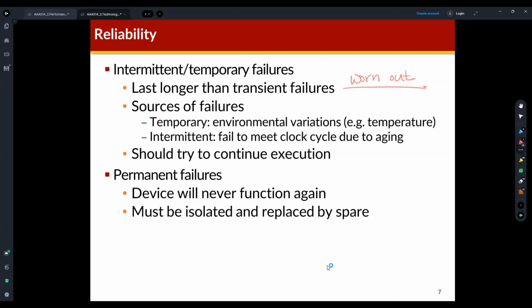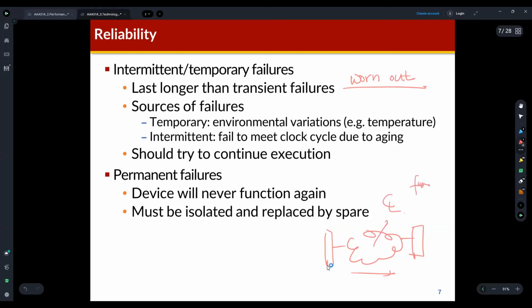If we use our processor chip for a long time, the performance, the clock frequency, which means the speed of the system, is affected. Actually, the delay of the combinational logic determines the clock frequency, right?